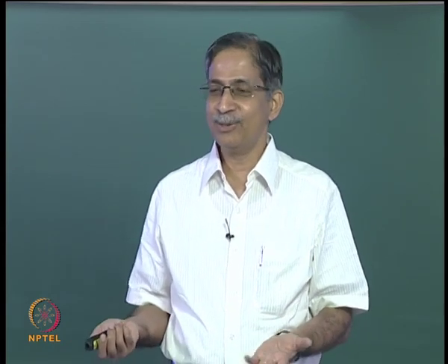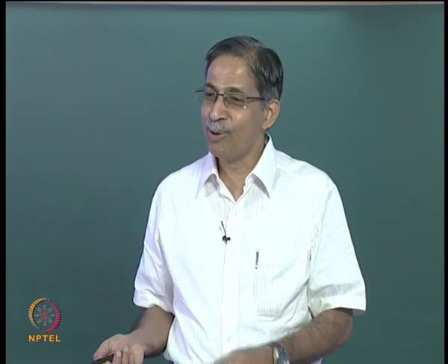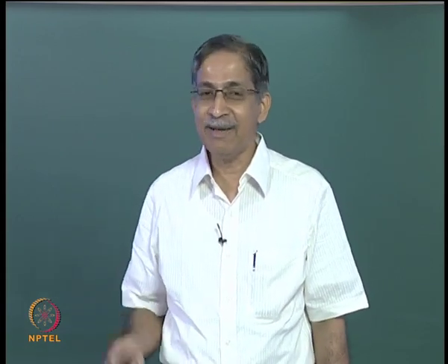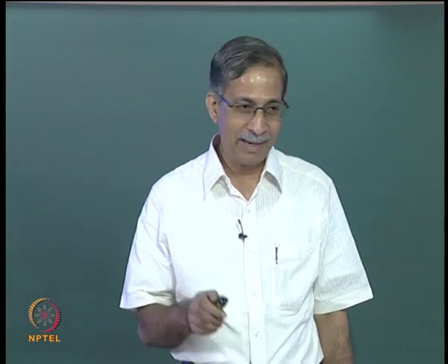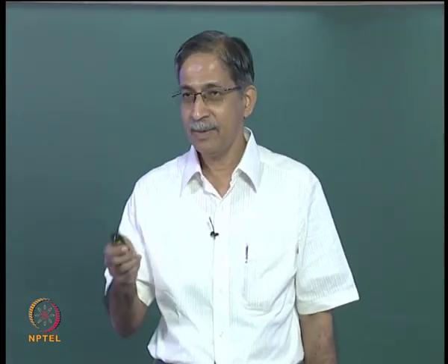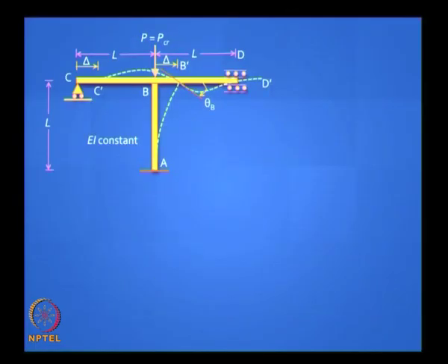So you have to just use your brains. First of all, you should know that in an unbraced situation you will never get a K value less than 1. So 0.7 is ruled out. It has to be greater than or equal to 1. Clear? Okay, so that's a good guess. Let's solve the problem.